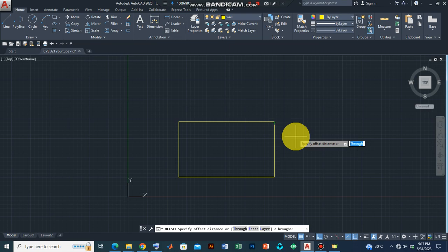Remember, we've set the units to millimeters, and we are drawing the external wall of the building. One thing we must also understand is that the offset feature is more like a parallel. So it gives the dimension. If, for instance, I type in 225, as can be seen on the screen, I press enter.